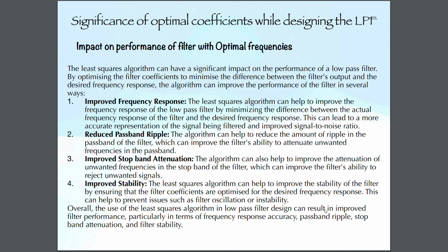The least square algorithm can have a significant impact on the performance of the low pass filter by optimizing the filter coefficients to minimize the difference between the filter's output and the desired frequency response. So here the algorithm can improve the performance of the filter in several ways.